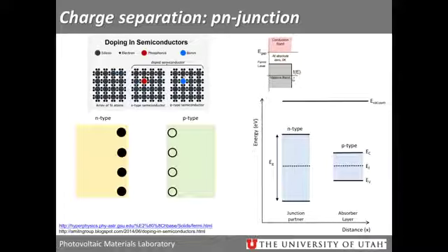Okay. So yes. So an intrinsic semiconductor, when the valence band is completely full, so you have no excitation, and the conduction band is completely empty, your Fermi level is at mid-band gap. So that's technically where your occupation probability is 50%, assuming Fermi statistics. Does that make sense to everyone?